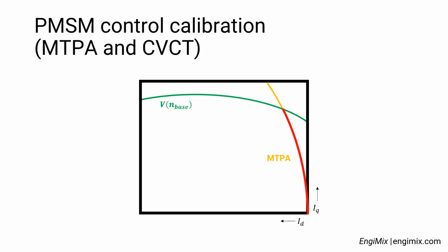When the speed achieves the base speed value at the considered DC voltage, all the voltage of the power source is used to compensate the back electromotive force and the voltage drop across the resistance of each phase. This means that after this condition is achieved, it is not possible anymore to increase the speed of the motor by moving on this curve.